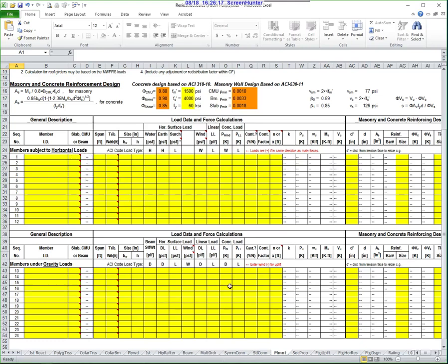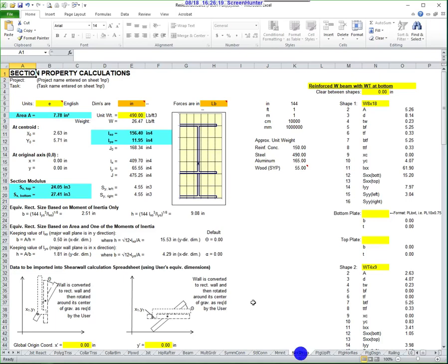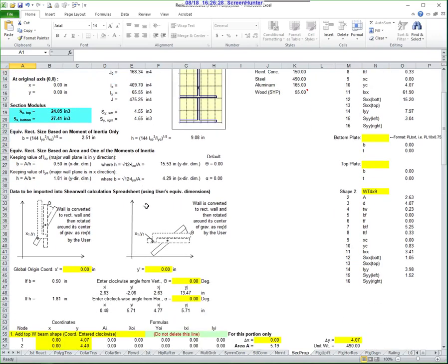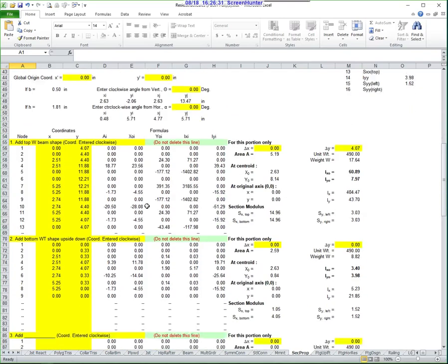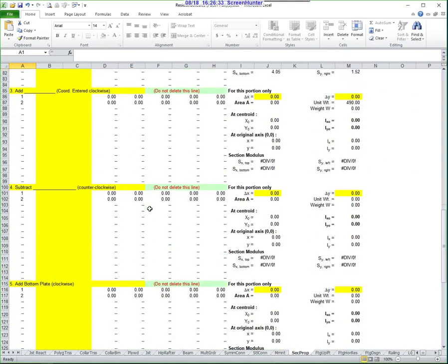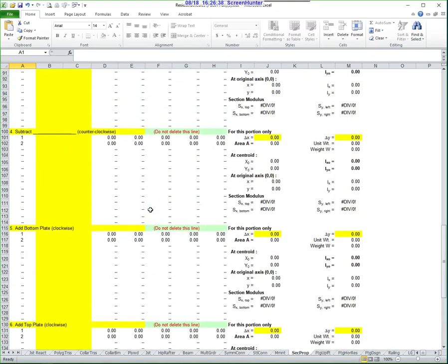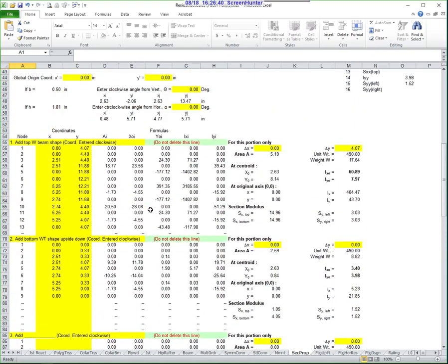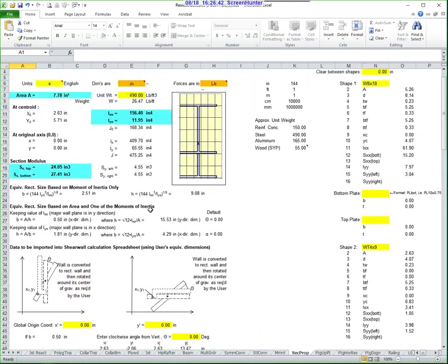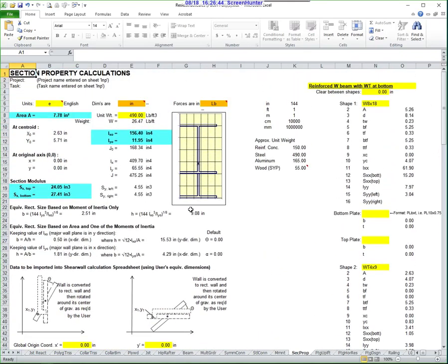SecProp, section property calculations. This module is also offered for free on the same marketplace where you purchased this program. The section property calculations use old well-known formulas and methods based on consecutive triangular shape properties added or subtracted along the trail of XY data entered by the user in any ordinary or orderly manner, knowing on a clockwise direction, starting and ending at the same point.